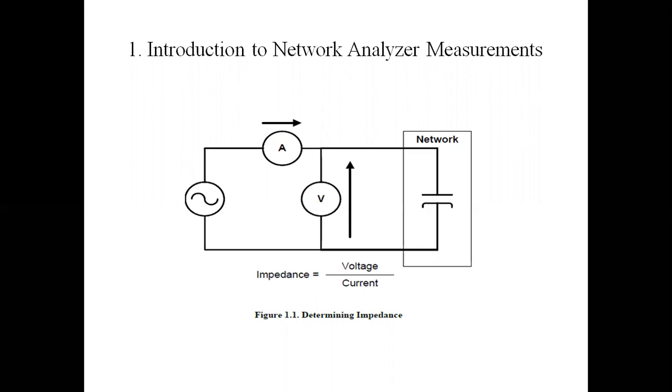Today, the VNA characterizes high frequency passive and active devices in their linear mode of operation by measuring their network parameters, called the S parameters, as a function of frequency. Over time, VNAs have been extended in hardware and capability to also measure noise parameters and nonlinear characteristics, including compression, intermodulation, and hot S22 measurements. As a result, the VNA evolved into an instrument enabling multiple measurements with a single connection.